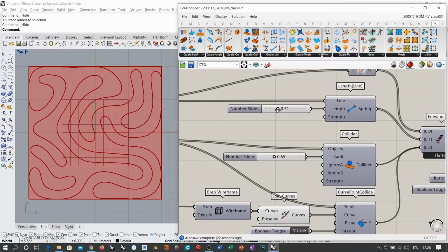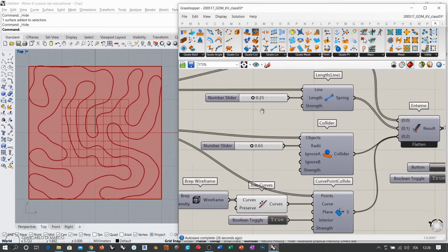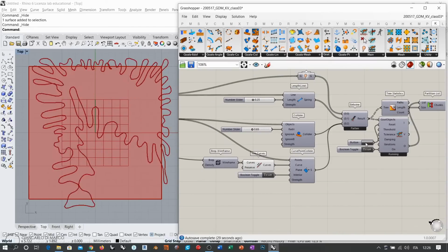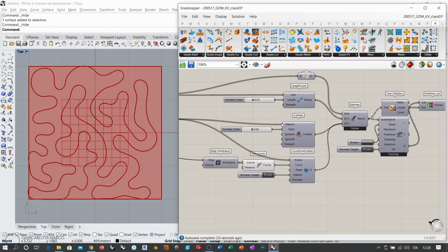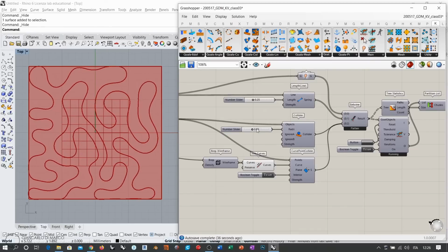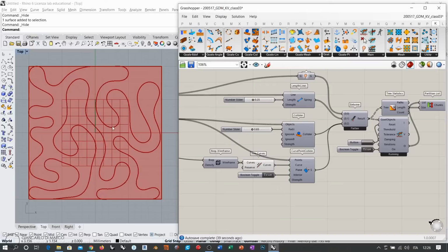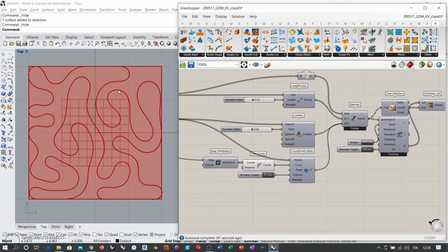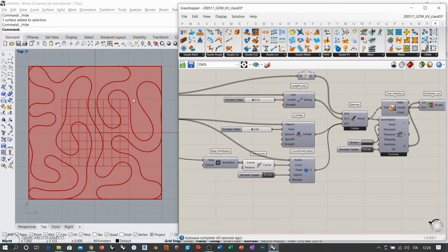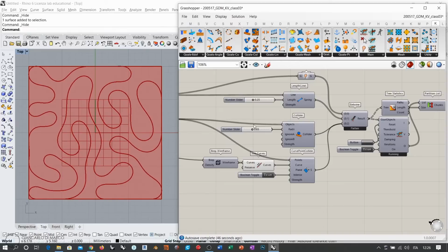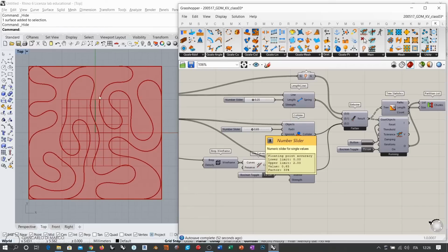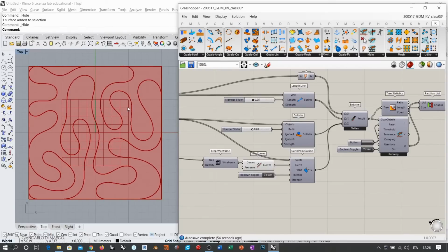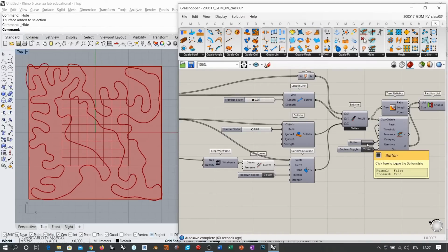And the other problem was that even if I go back here to 0.25, let's say, if I reset this, you see that this curve is actually exploding. Now, I do not recommend this for another reason, because the collider, well, actually, yes, it keeps each part of the curve away from another part, be it 2 consecutive vertices, or 2 vertices getting too close together. But it also produces a very fast expansion, and this could eventually make the curve self-intersect during the expansion phase. So you see that during the expansion phase, there is a lot of chaos going on.